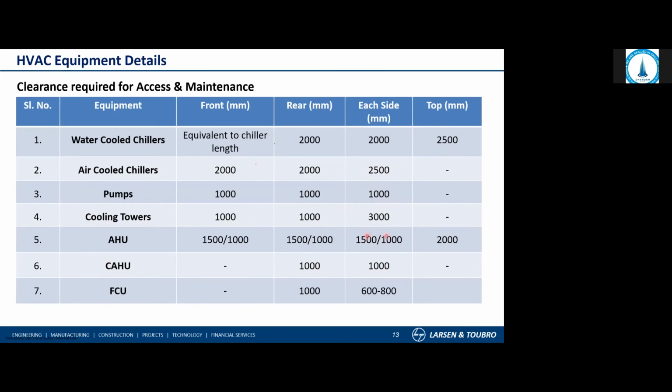Air handling units, obviously, are a very important part while doing the AHU room sizing. If you check the requirement of AHU room space and the clear space for the AHUs, there will be chilled water pipe connections, motor removal, and blower removal access space for the air handlers. Accordingly, we have to see what the coil size, blower and motor size are, and which side of the AHU we are providing chilled water pipe connections. We need suitable space to remove the equipment from the AHU for future maintenance. It is very important to keep this in mind and incorporate it in the design.